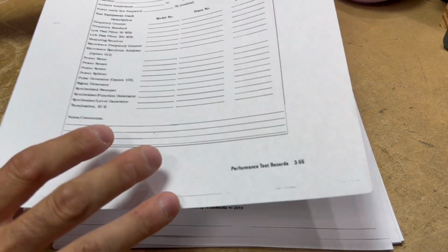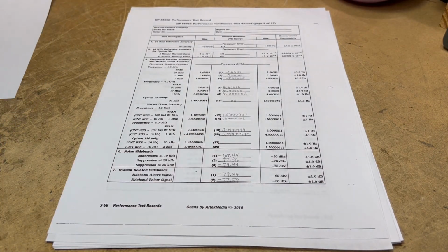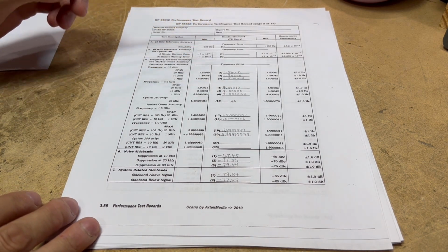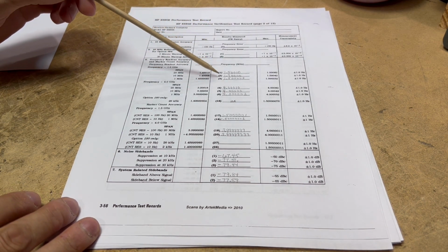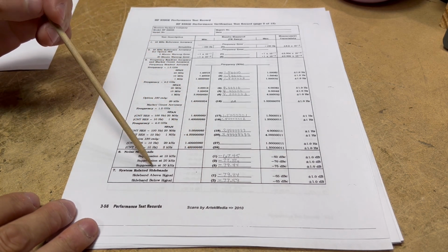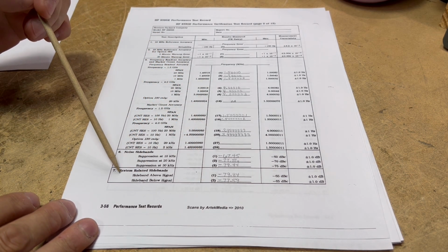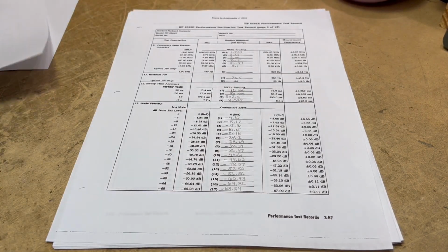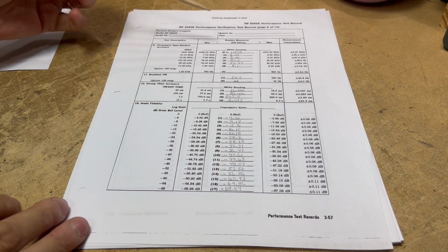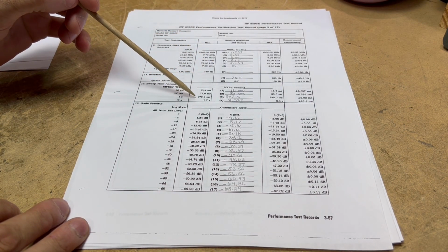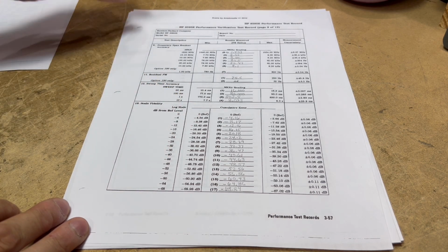And we'll focus on the measurements that we actually made changes to. Here's the frequency readout accuracy marker and the marker count accuracy here. No issues. Measured noise sidebands and system-related sidebands, no issues there. Frequency span readout, no residual FM, sweep time accuracies, and scale fidelity.